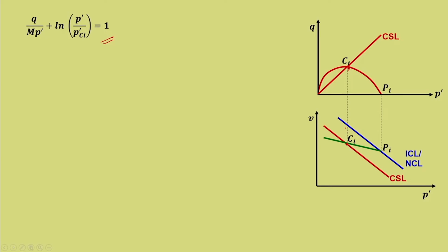So, what is the relationship? That is what we are trying to understand. When we understand the Cam-Clay model, we need to keep these aspects in mind, then only it will work. So, Ci is the point where the yield curve intersects the critical state line, as shown here. Now, you also need to see that this unloading line represents elasticity. The yield curve also defines the domain of elasticity. So, the crossing point is Ci.